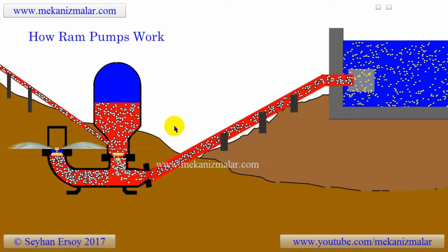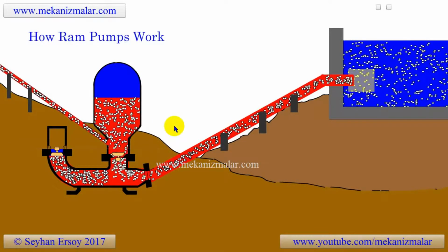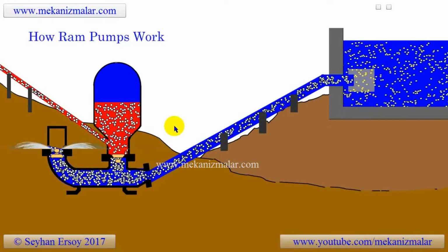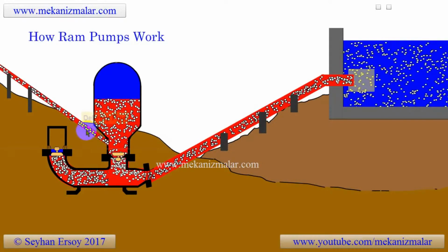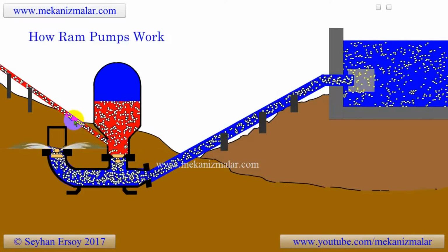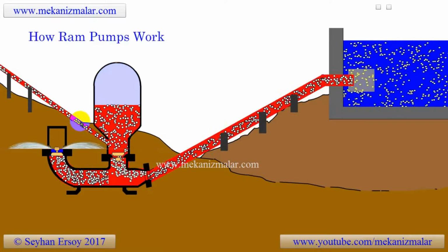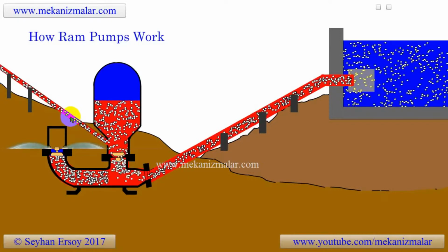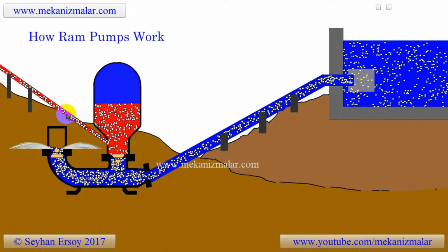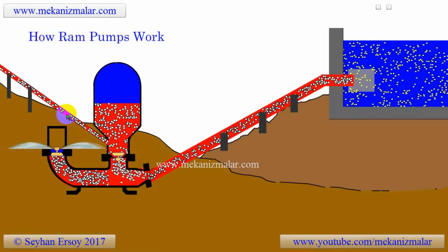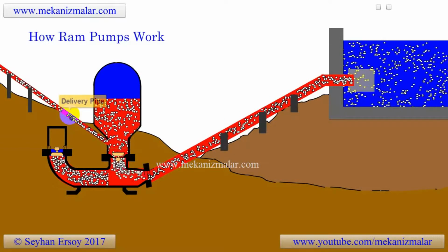When the waste valve opens, the delivery valve closes and vice versa. However, the water continues to flow through the delivery pipe, and this is due to the pressure of trapped air inside the accumulator. The accumulator acts just like a flywheel and regulates the water flow rate through the delivery pipe and takes pressure spikes from the system.